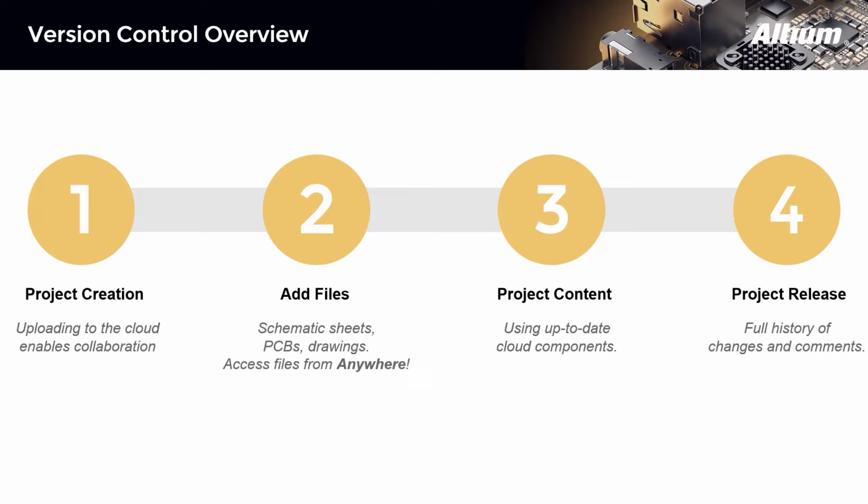The components are placed on the schematic sheets and transferred to the board for routing, but we all know this process is not performed in a single iteration. Whenever you save your files, you can commit them to the server to provide a snapshot of files, allowing you to revert any changes easily.